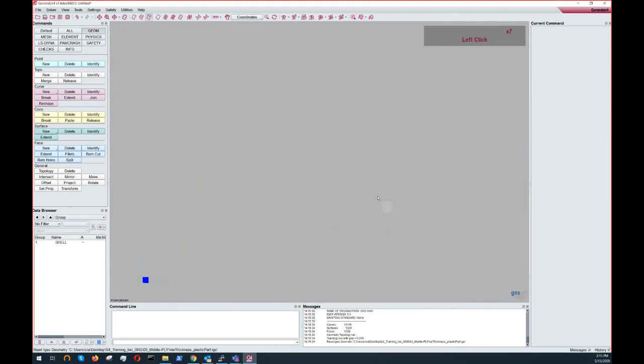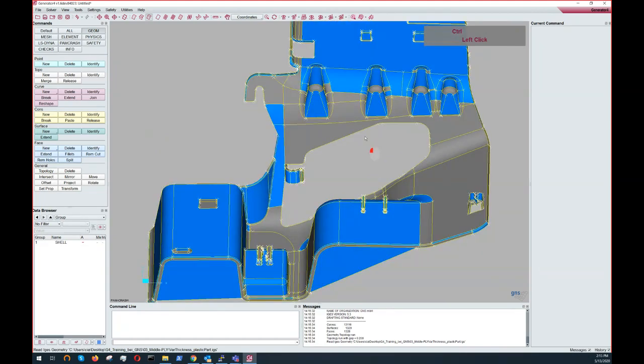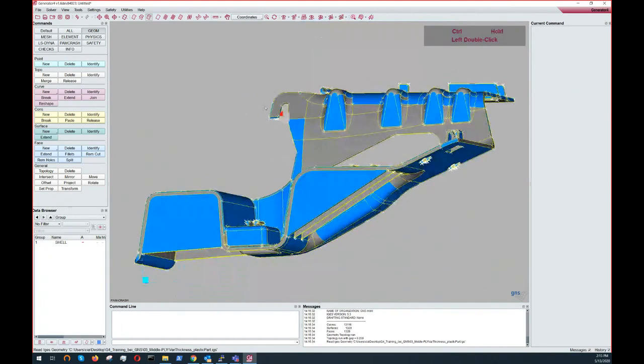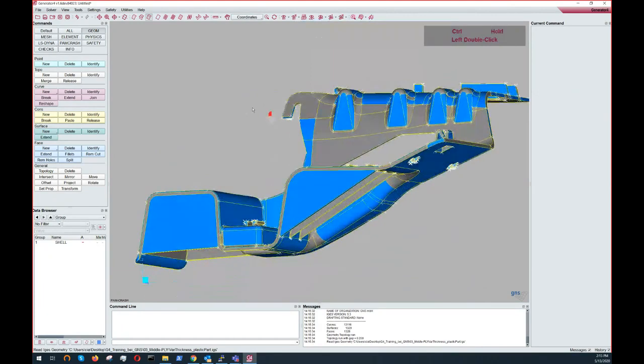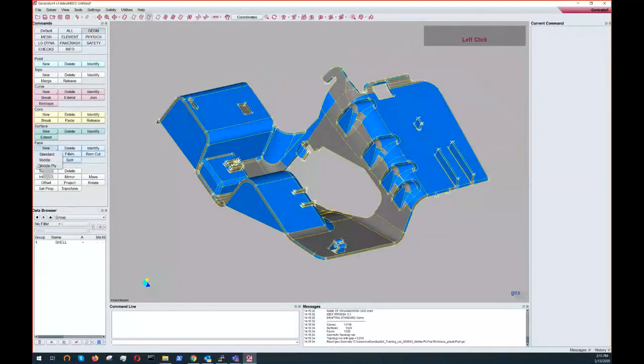And I import it just as I imported the first one. Complex geometry. And I will create the middle ply for this. So one interesting thing always before using this middle ply command is the middle ply has default values from maximum thickness of 3 millimeters and rounded edge radius of 1.